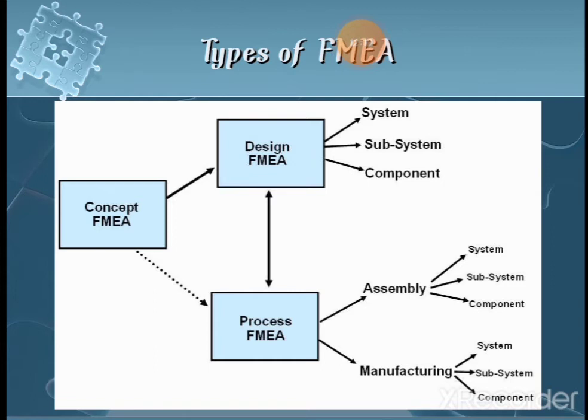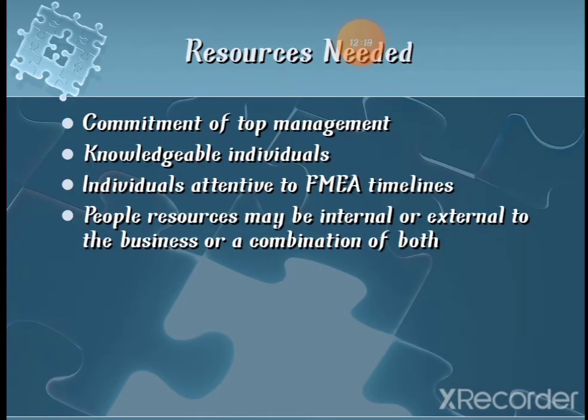Okay, there are various approaches for FMEA. We will see some of them, such as the bottom up approach. The bottom up approach is used when a system concept has been decided, when the initial concept of the system has been decided. In this, each component on a lower level is studied one by one.